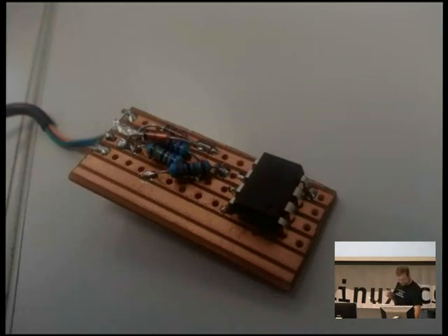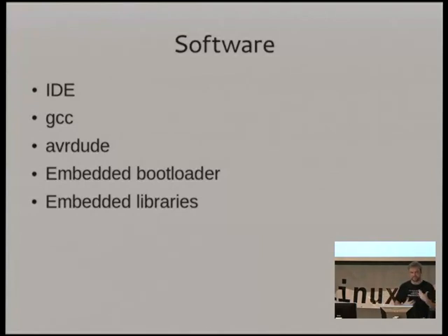Anyway, moving on. So going back to the software as the next step. It's got the IDE. The IDE really actually calls down to GCC to do the bulk of the compilation. And from there, it calls over to a bit of software called AVRDude, I'm sure there's a good reason for that, to actually flash the firmware into the chip. So when you do your Control-Shift-U or whatever it is in the IDE, that does the compilation using GCC, and it does the flashing using AVRDude.